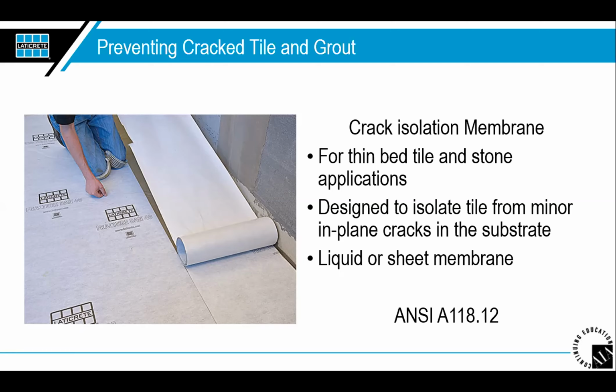But when you do that, again, check with your manufacturer recommendations, because I've seen it done where installers will come in and put a 6-inch band over top of a specific crack that's running all over the floor because there's no other spider cracking occurring. Okay, well, that's great. I still wouldn't agree with you. I would assume that even if that floor was 20 years old, it's still moving and it still has the potential to crack, right? We know concrete's going to do two things: get hard and crack. There's no doubt about that.